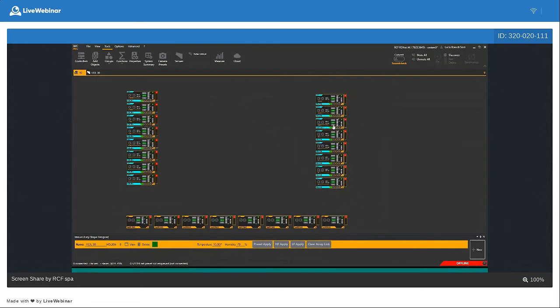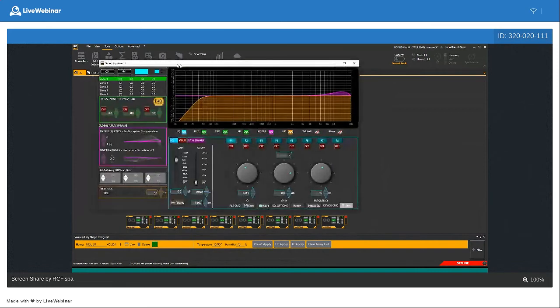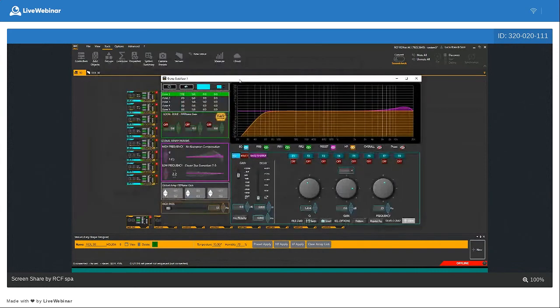So clicking on the EQ button of any icon will be exactly the same thing. And the equalizer will open. Not just the equalizer, the internal DSP of our clusters. As you can see, we have the pink line, which is the line coming from our design. So with this correction about high frequencies and no correction about low frequencies.